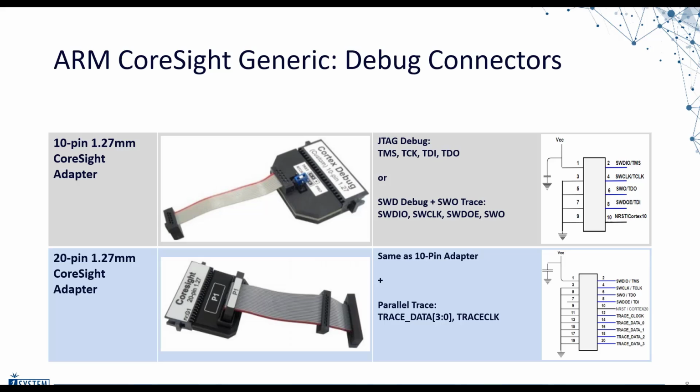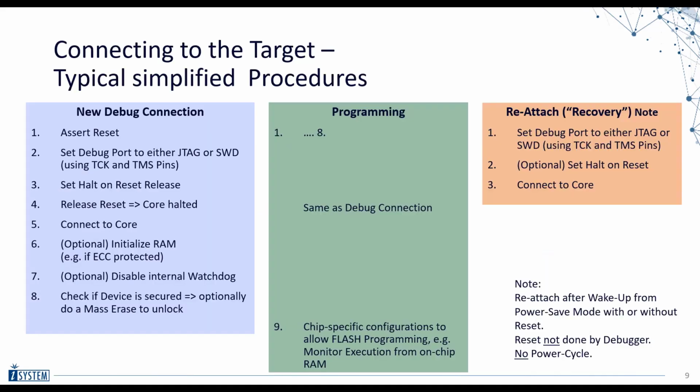For more flexibility, most controllers offer multiple options for multiplexing the parallel port pins to avoid conflict with application IO functions. With this slide, I want to give you an introduction to what happens when a debugger like winIDEA connects to a Cortex-M4 based controller. So I will distinguish three different scenarios for establishing a connection.